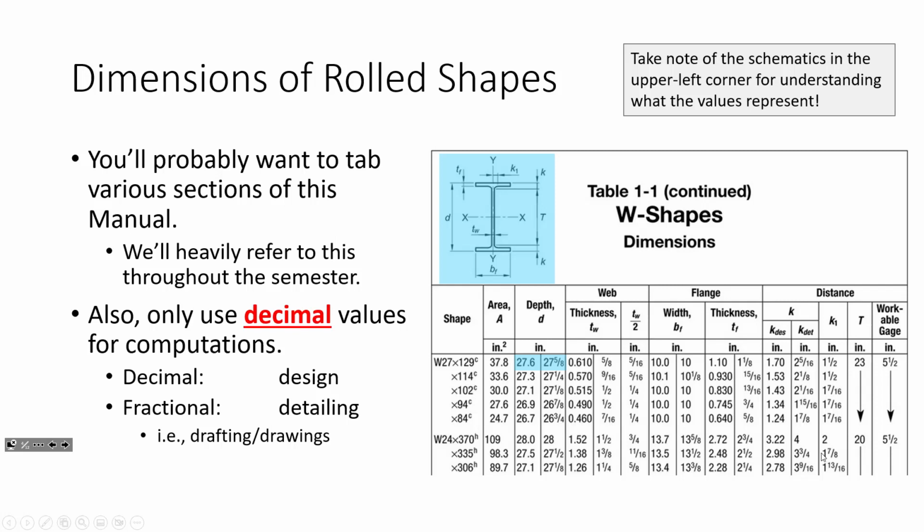One of the things that I will say about steel design, and this is kind of true about structural engineering, I think structural engineering can really wear this with a badge of honor: it does a really good job of maintaining consistent notation across the board. If I ever use the symbol B sub F, it always means flange width in just about any specification related to structural steel design, whether it's the building spec or the AASHTO LRFD bridge design specification.